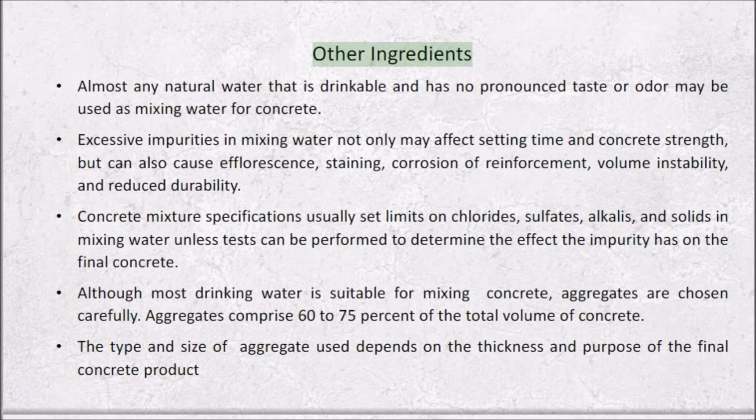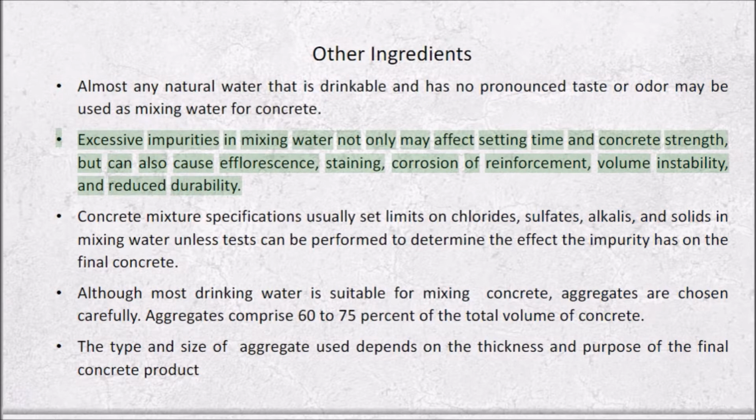Other ingredients. Almost any natural water that is drinkable and has no pronounced taste or odor may be used as mixing water for concrete. Excessive impurities in mixing water not only may affect setting time and concrete strength, but can also cause efflorescence, staining, corrosion of reinforcement, volume instability, and reduced durability.